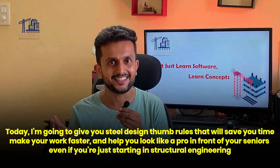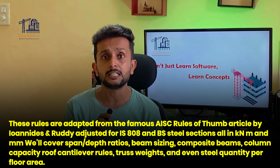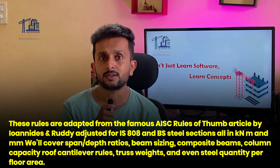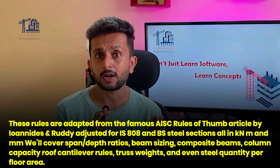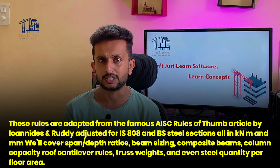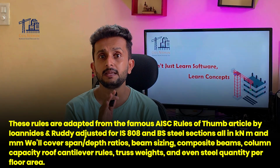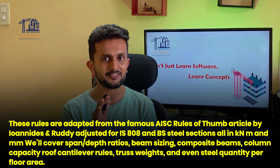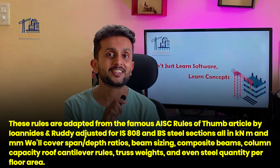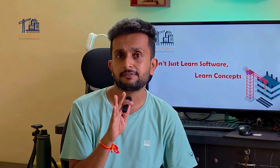These rules are adopted from the famous AISC rules of thumb articles by Leonis and Rudy, adjusted for IS 808 and BS steel sections, all in metric units. We will cover span by depth ratios, beam sizing, composite beams, column spacing, roof cantilever rules, truss weights, and even steel quantity per floor area. So let's first start with the depth ratios.